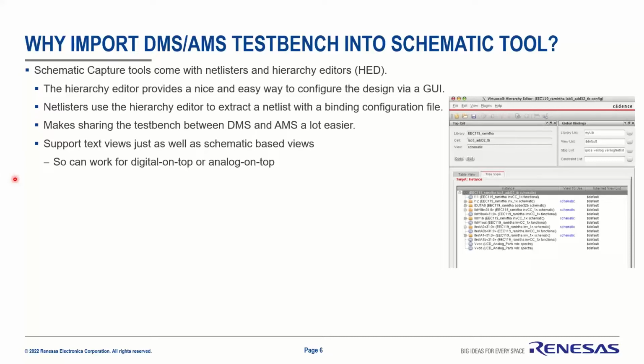The hierarchy editor is a nice and easy way to configure the design via a GUI and actually see what different views you're using for different instances. You can do that in a Verilog configuration file, but it's not visible in the sense that you can see exactly what you're getting.